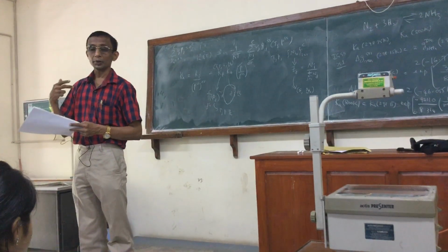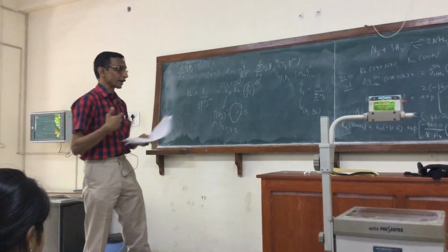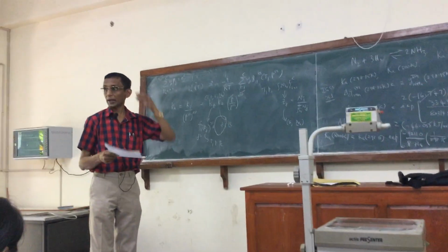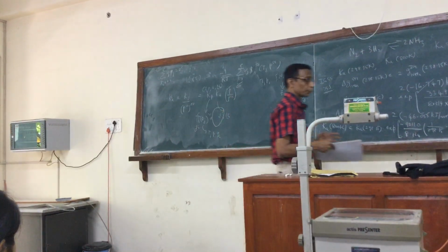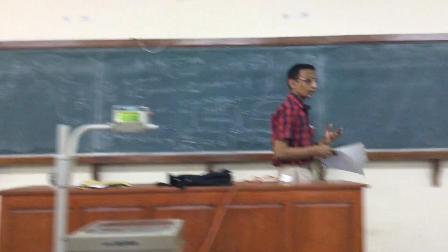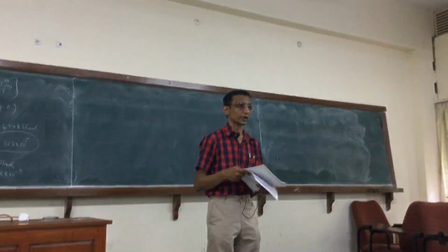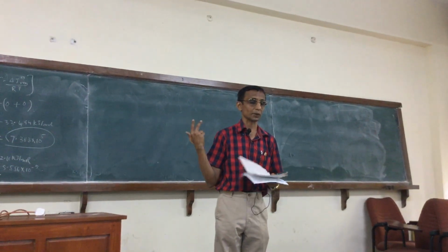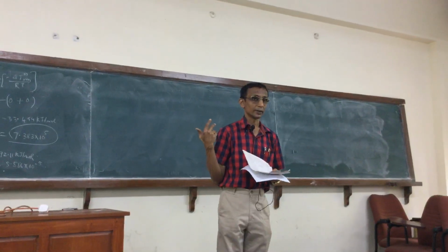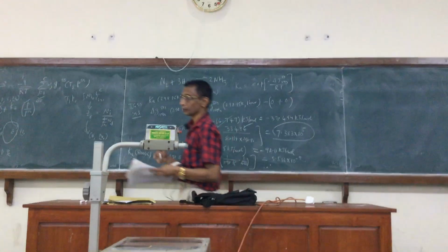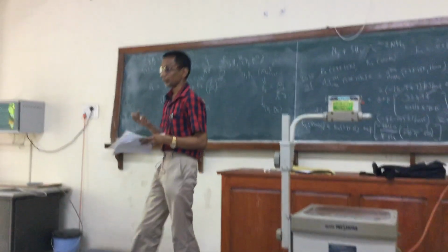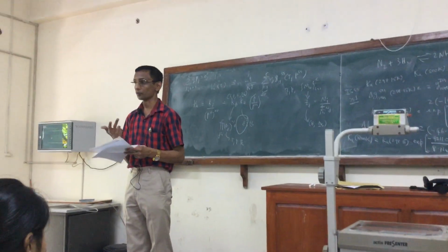The equilibrium conversion will also decrease, but because these reactions have to be carried out in reactors with a certain optimum size, we cannot keep the temperature very low. If the temperature is low, the equilibrium conversion might be very high, but the rates will be so low that we will need enormously huge volumes of reactors.